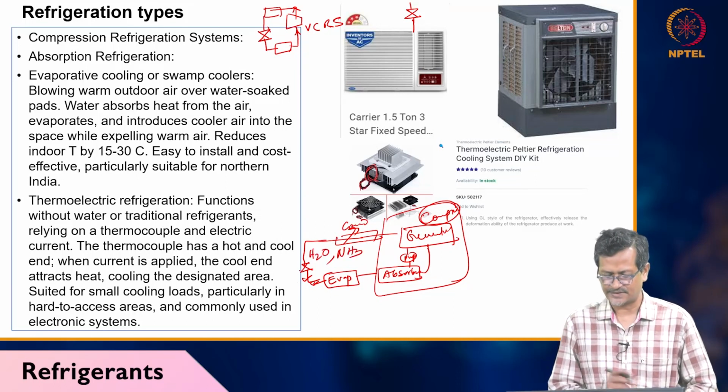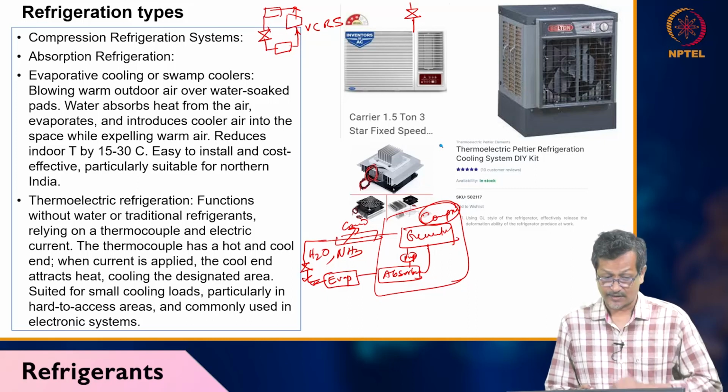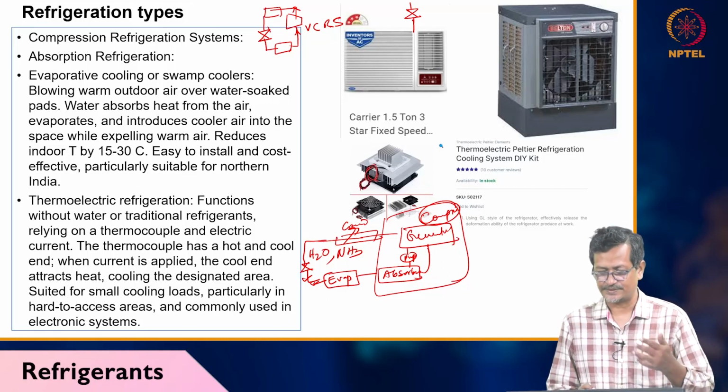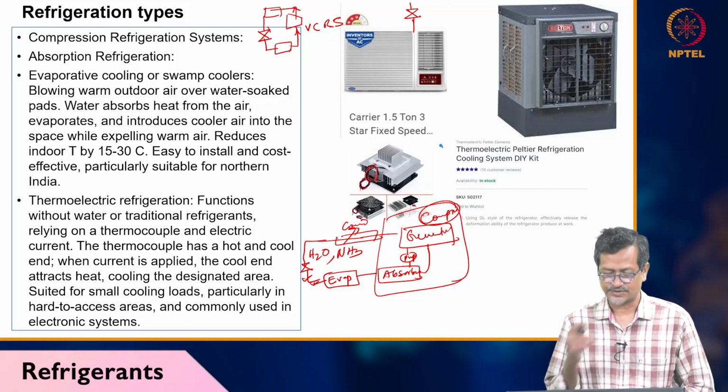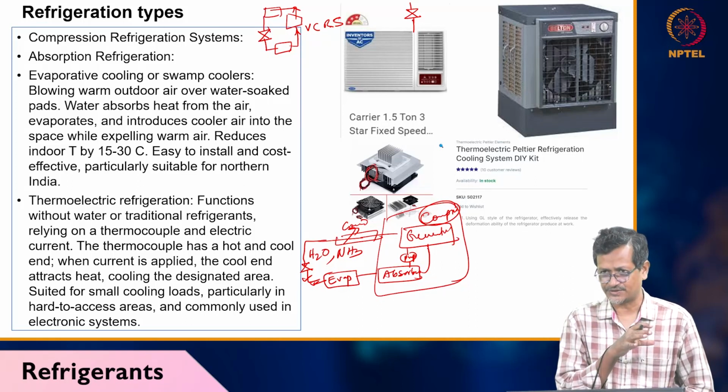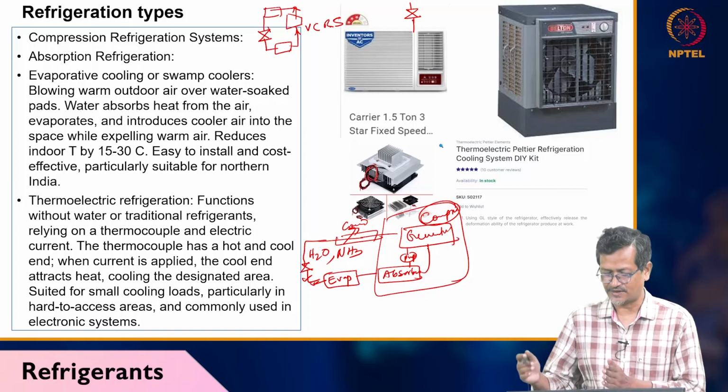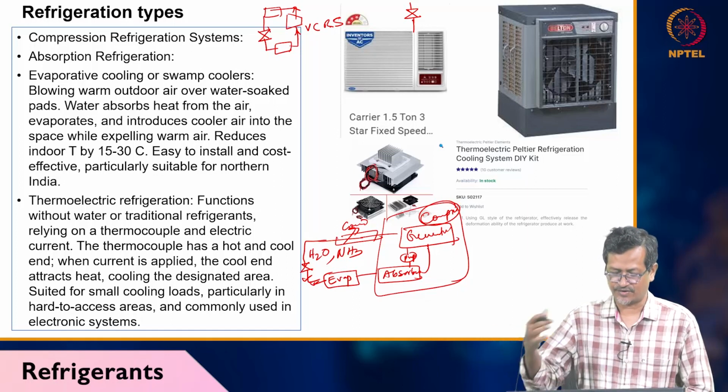Okay, so basically these are common refrigerants used for vapor absorption systems. Normally this will be used for cold storage or similar applications where a high heat requirement is there. These systems are heavy and bulky, so you cannot use them for small room applications, because you will have extra mechanisms: absorber, pump, generator, then condenser.